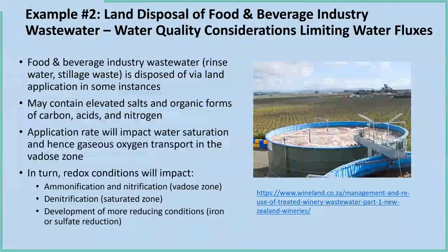In California, where I live, operators of these facilities can obtain permits to dispose of food and beverage production processed wastewater on the land surface, provided that the operator can demonstrate minimal adverse environmental impacts to the underlying groundwater. So consider a situation where a significant unsaturated zone exists beneath the release location. A slow discharge of processed wastewater will percolate slowly through the vadose zone, with organic nitrogen eventually oxidizing to nitrate, which is an undesirable groundwater constituent at elevated concentrations.